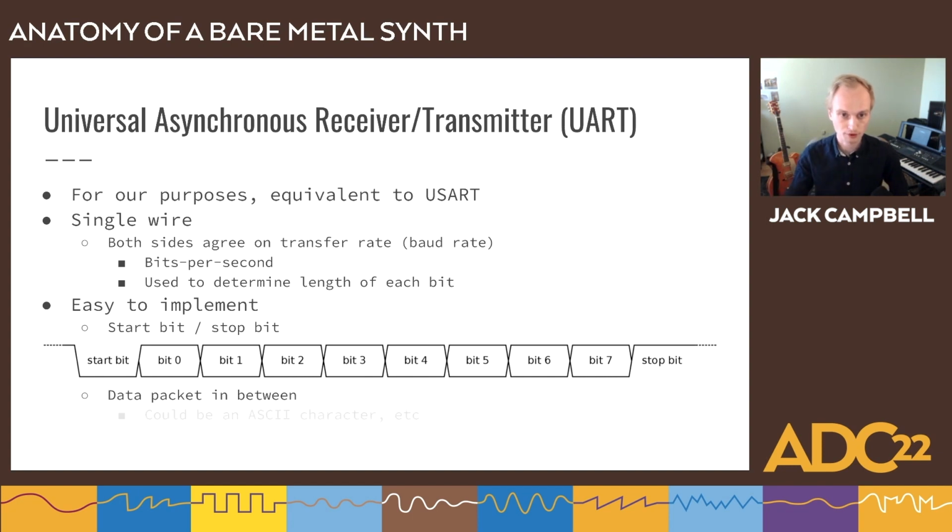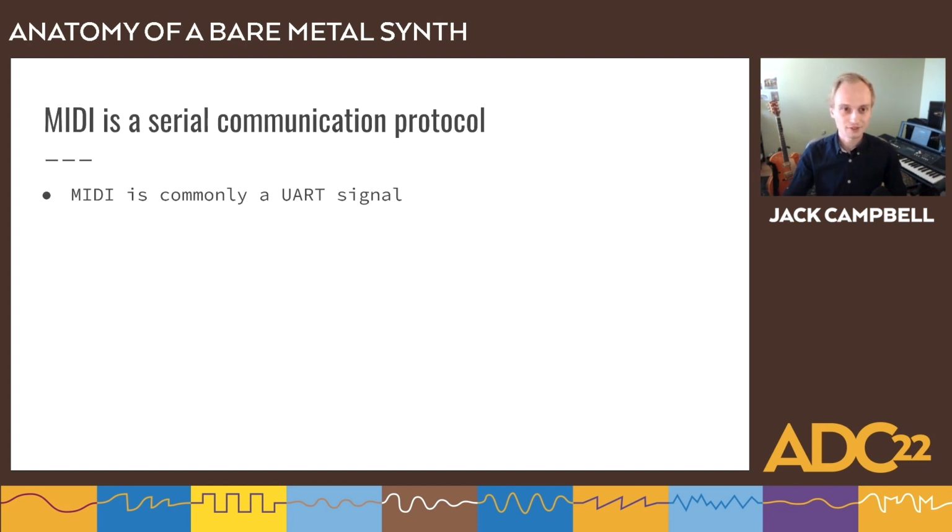We'll talk about MIDI more, but like I said, it's really popular to use this protocol early on because it's one wire and it can have ASCII characters for debugging your other subsystems pretty easily. But we can send MIDI this way. And so MIDI is commonly sent over UART.